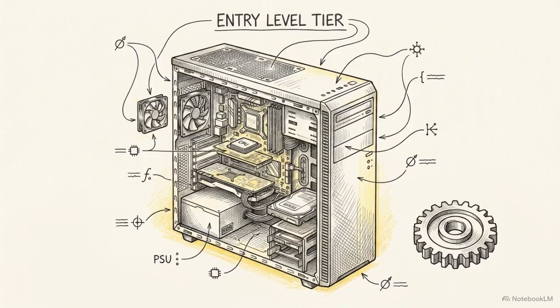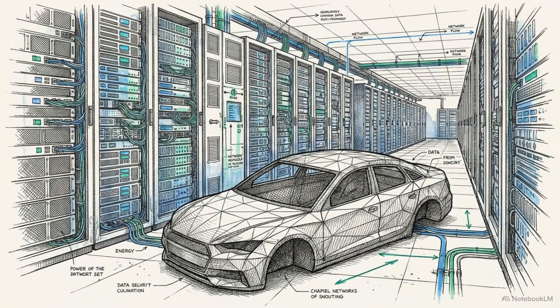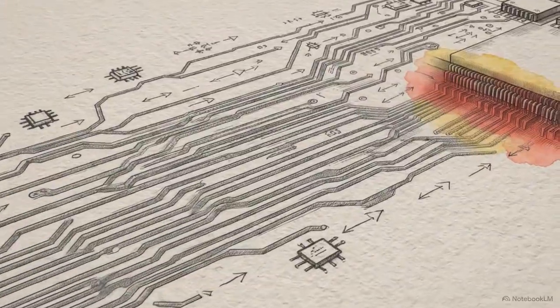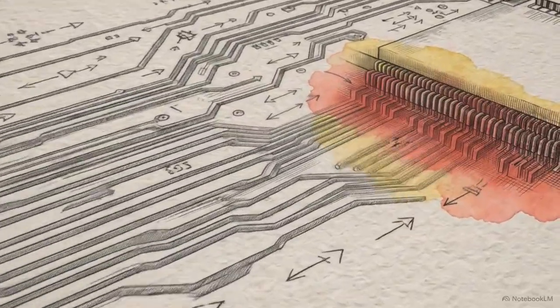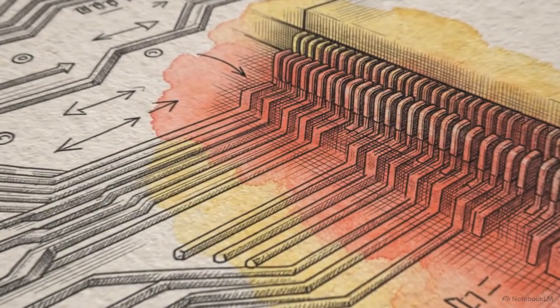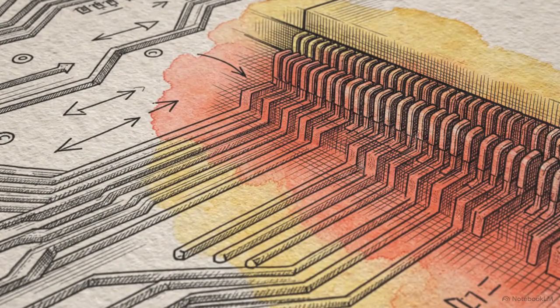A standard workstation with 64 gigabytes of RAM is perfectly adequate for learning or reviewing small components, but a full vehicle crash demands specialized server architectures designed to provide immense memory bandwidth. The ceiling for explicit solvers is ultimately set by how quickly the motherboard architecture can move data, rather than how fast the processor can calculate.